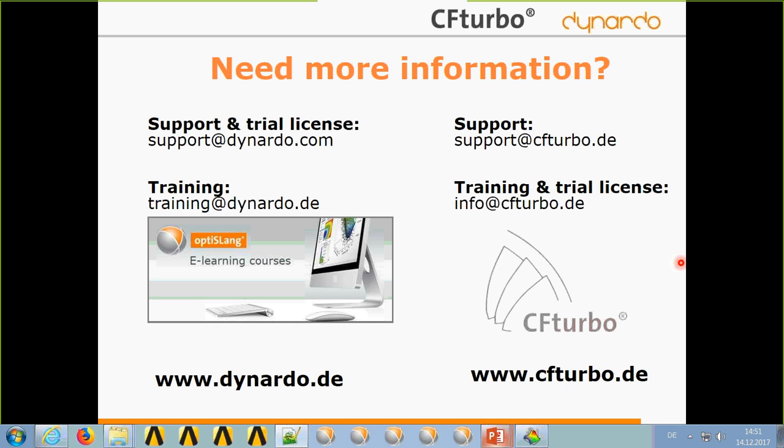The interface, the process integration may always look a bit different. For example, for Pumplings, you saw that you can use the text-based interface, or for StarCCM+ as well. For CFX, you can also use the Workbench node, for example, where we directly connect to a Workbench project, or you can work with the standalone CFX version. So optiSLang is providing interfaces to all the different CFD solvers.